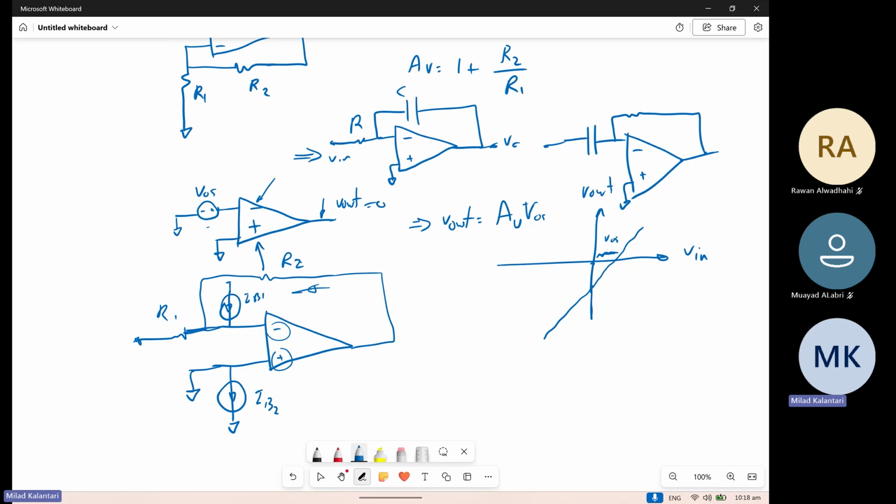So if you see this, the impedance connected to the negative port is R2 almost in parallel with R1, just roughly, right? So to compensate the other side, we try to have the same resistor connected to the ground instead of just directly making it a short. What will happen is the current passing through this parallel R2 and R1 basically changes this voltage, which we didn't expect.